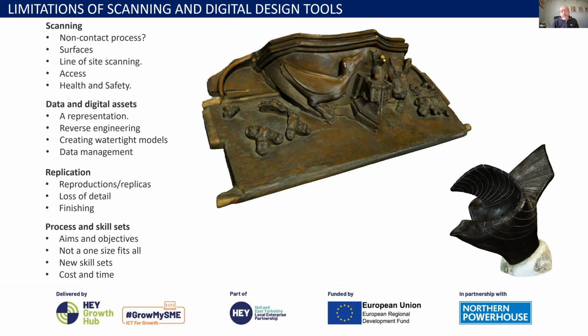It's also got better where, if you want to create a 3D print, you have to create what we call a watertight model. That used to be a big issue, but I'm increasingly finding it's less of an issue as the software is getting smarter at finding holes and plugging those holes. If it's got a hole, then the 3D printer won't make it. It tends to fall over and keel over. It has to be watertight for it to make that geometry.